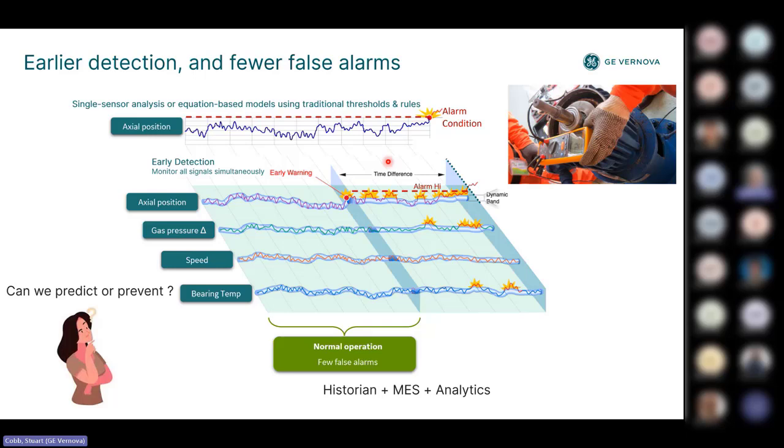So maybe you have excessive vibration on a pump, and it may be something as simple as one or more of the bolts holding it to its pad have started coming loose, and it needs to be tightened down. But the bottom line is, using analytics, we can start providing early warning indications that there might be a problem, and it might not be with just this one variable.